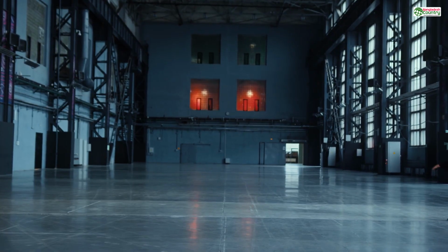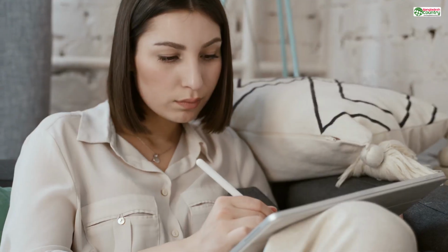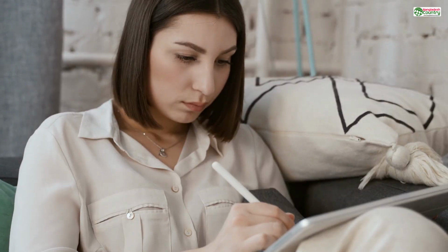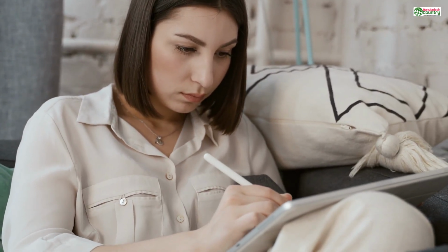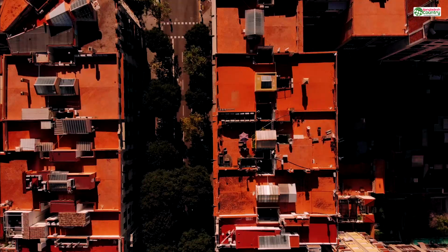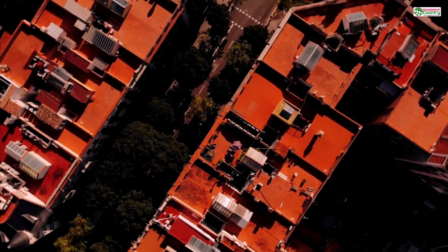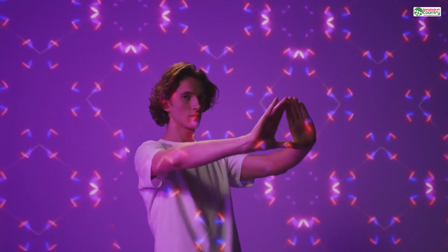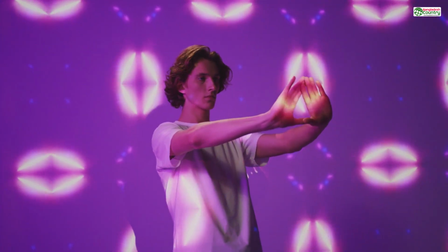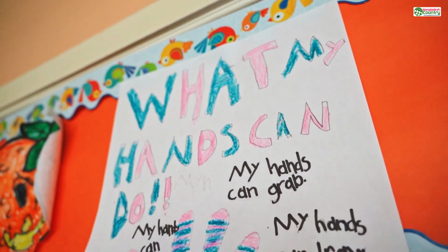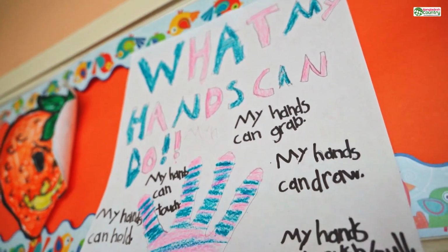So how do you choose? It's not about memorizing specs. It's about asking 4 simple questions. Question 1. Is this for looks or for function? If it's a visual model that will sit on a shelf, your primary choices are PLA for its cost and color options, or standard resin for its ultimate detail. If the part has to do something, you immediately look towards PETG, ABS, nylon, tough resins, or metals.